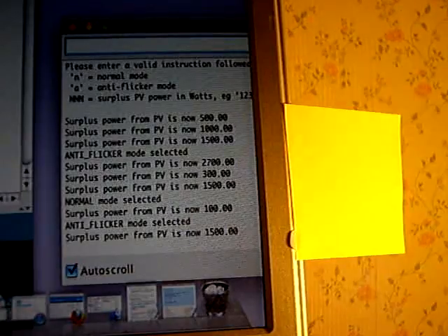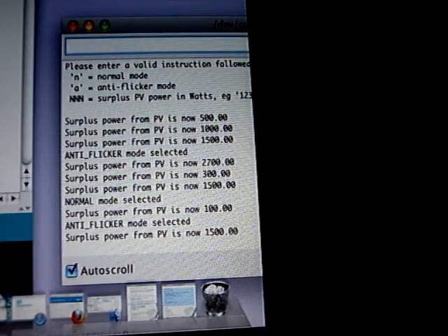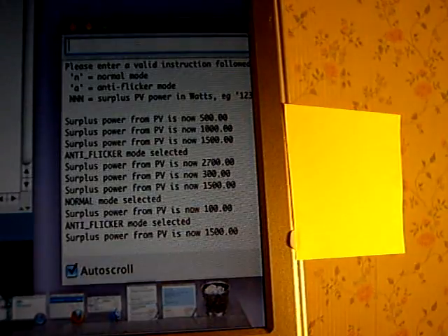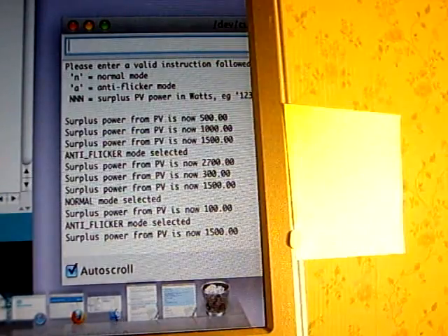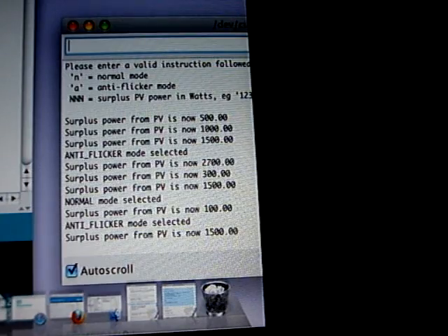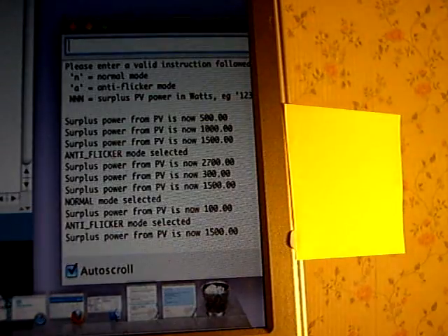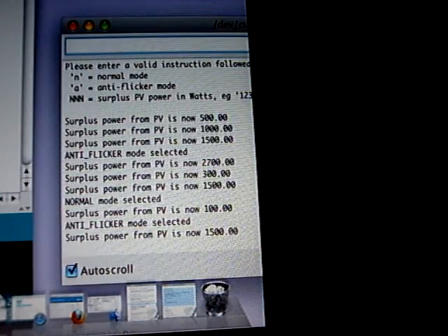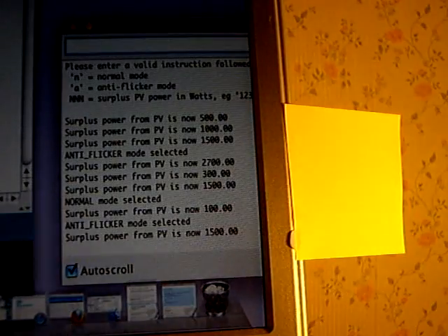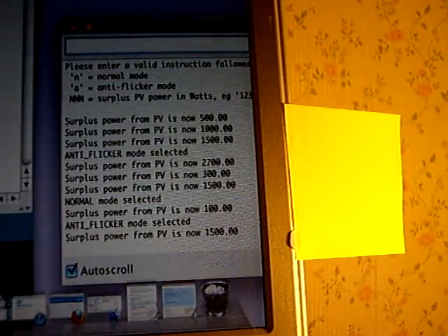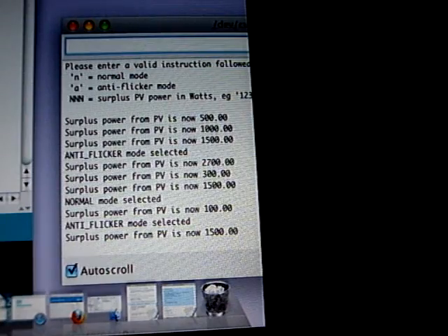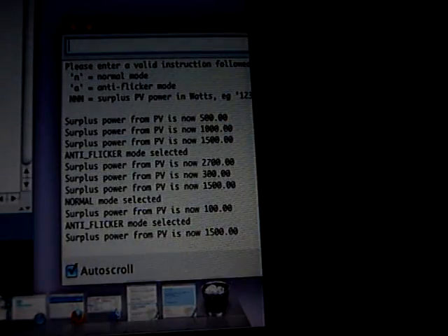There is a known frequency at which this system should be toggling, and if this was a real system rather than a simulated one, and it's not toggling at that rate, well, you would need to alter the power cal factor until it does. So once you've got the system toggling on and off at the right rate, then you know calibration is correct. So that will be a very easy way to calibrate a Mark II type system which has this anti-flicker mechanism in there.